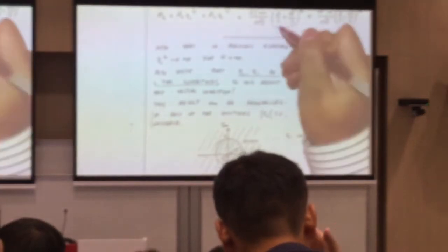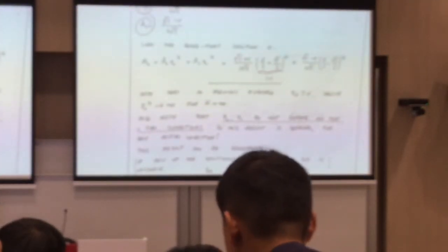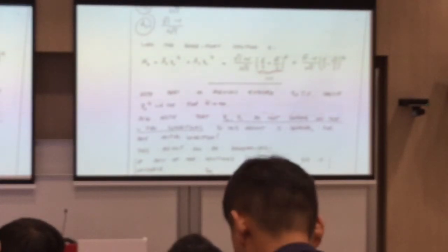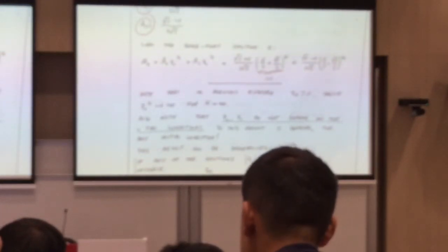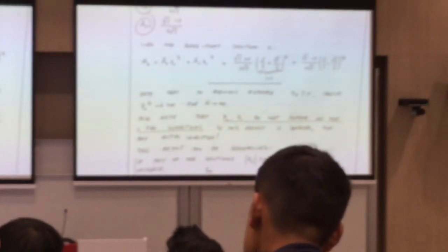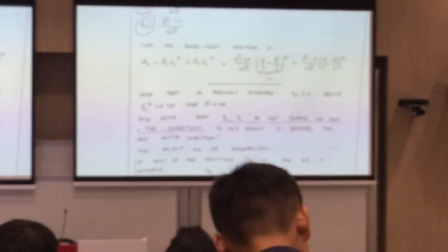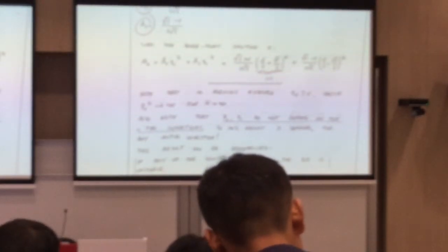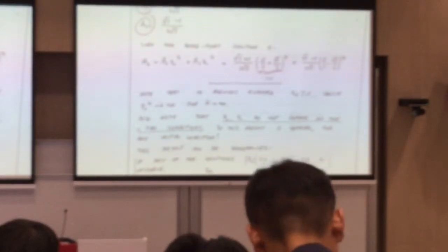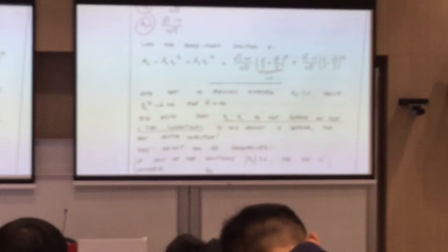So for this one, if you notice, there is one which is outside the unit circle, then it's unstable. And how do we know whether it's outside or not? If you have a complex number, what should we do? You should calculate the length. You calculate the radius, using your imaginary part squared plus your real part squared. This is something you already know, right?